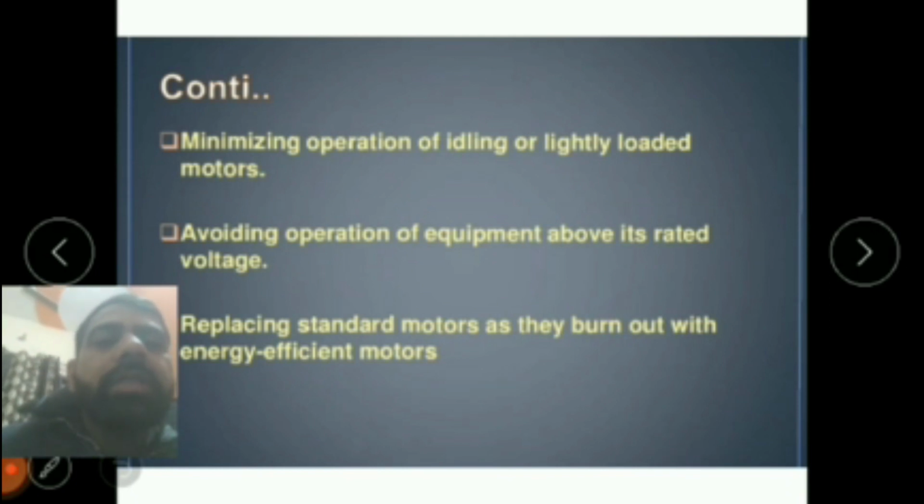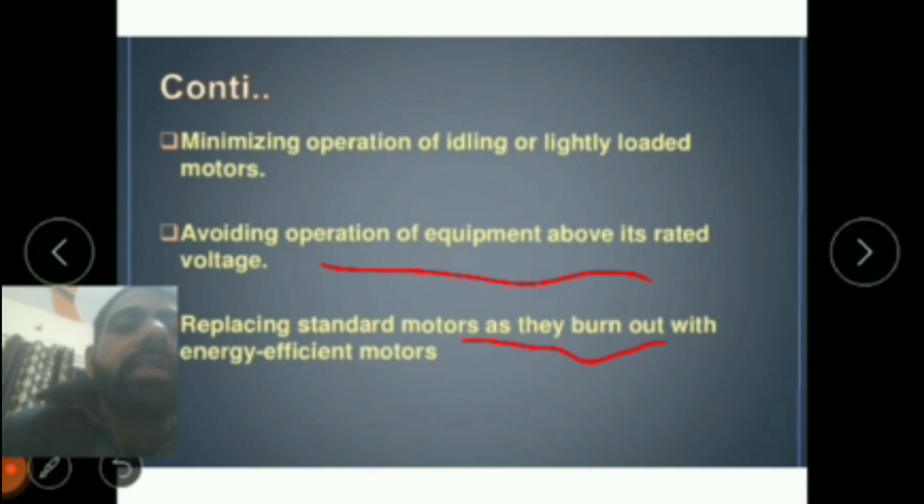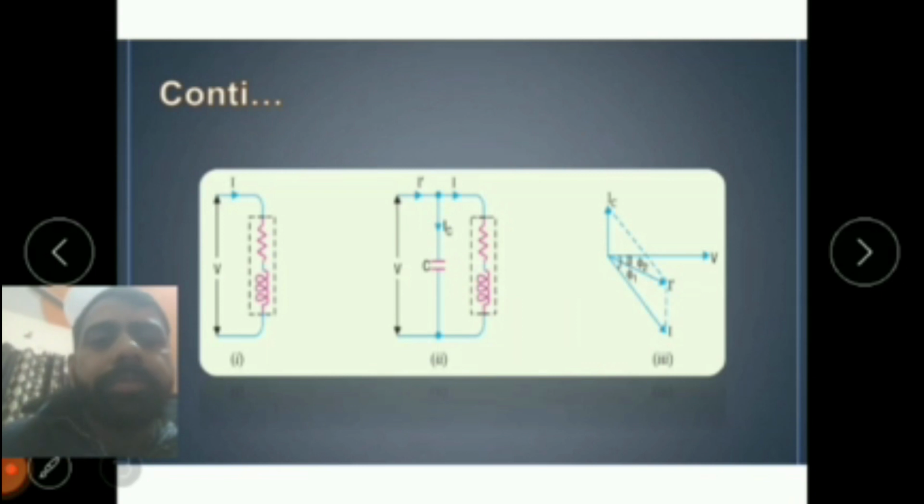Another method is minimizing the operation of idling or lightly loaded motors. It will also avoid the operation of equipment above its rated voltage, and replace standard motors, as they run out, with energy efficient motors. So these are other methods to improve the power factor as well.